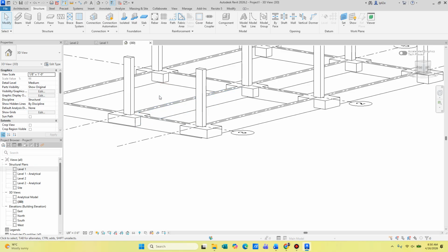So it will be pretty simple. You just have to make sure that you're using the correct size, the correct dimensions, and set up the grid lines properly when it comes to the structural modeling. Because if you're running a structural analysis, the idea is to define the structure into this beam system and the framing system, and then you put all the dead loads, live loads, run the structural analysis, and make sure that the structure can withstand all the additional forces and doesn't collapse on its own.